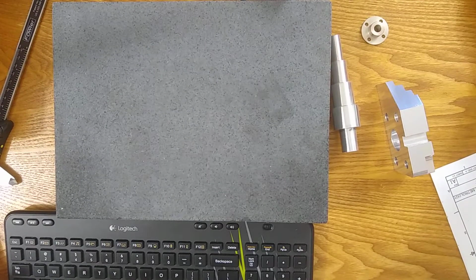I'm not going to cut them out because mistakes happen. I'm just going to own up to it. But I should have had a box around the 2.5 and the 0.5, because I want to put a true position requirement on that hole. So I neglected to do that. So I'll have to rev this print up. If this were a real world situation, it would rev up to A3 or B1 or something that makes sense.